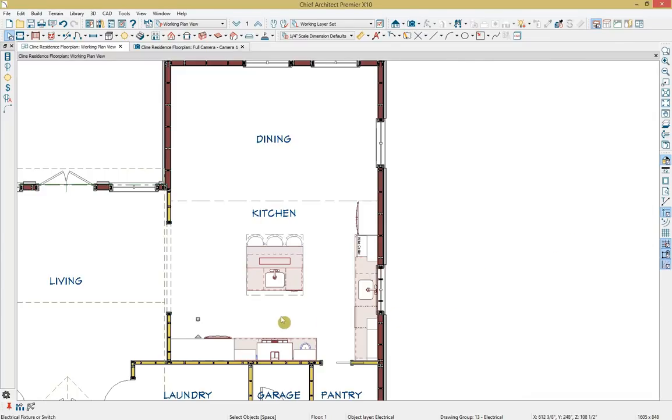So now to multiple copy those lights, I'm going to come over to our light, and notice that once I hover over it, my mouse changes. And then to activate our mode that uses both the primary and secondary distribution behavior, I'm going to right click and hold my right click on my mouse and evenly distribute those lights across. And then once I'm satisfied with their location, I'm going to release my click, which now activates my secondary distribution behavior, and then I can just drag those 4 copies out. And once I'm happy with those lights location, I can just click once, and now we have all of our lights distributed.